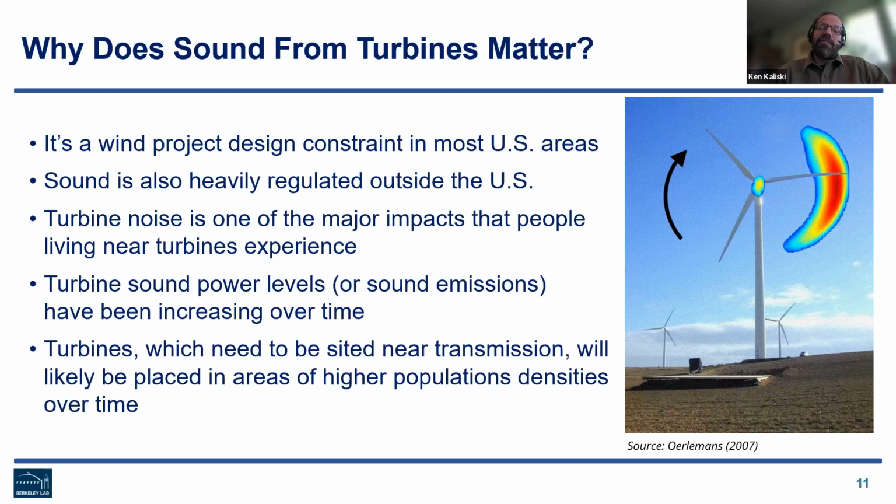But why does the sound from wind turbines matter? Well, it's a design constraint in most US areas, and certainly outside of the US as well, where you have noise regulations, you have people concerned about noise, you have people concerned about the height of the wind turbines. So it's something that is definitely very much considered in permitting wind projects and after they're permitted as well.